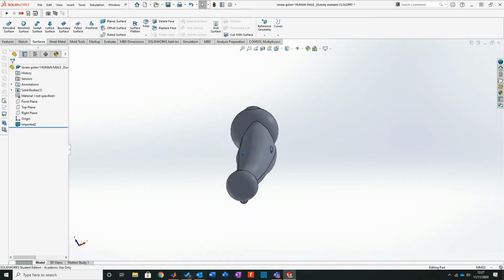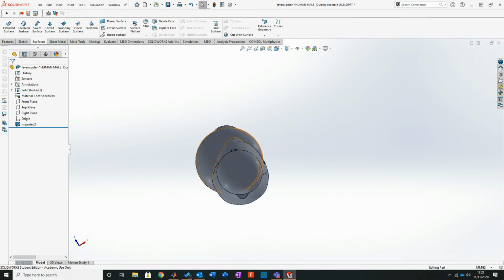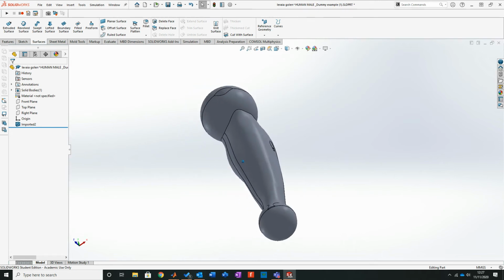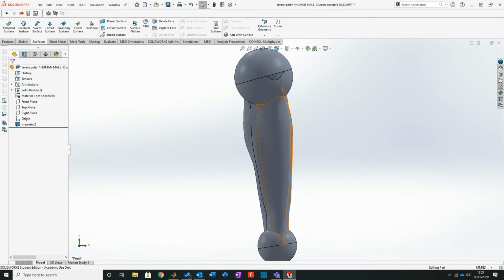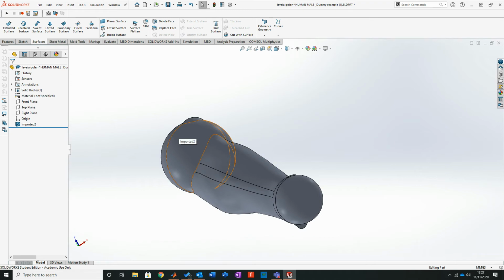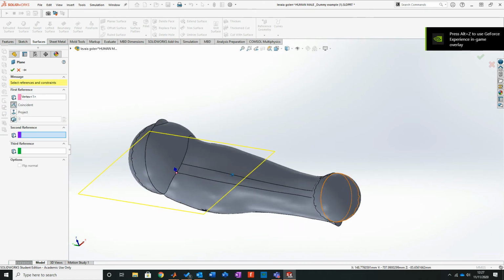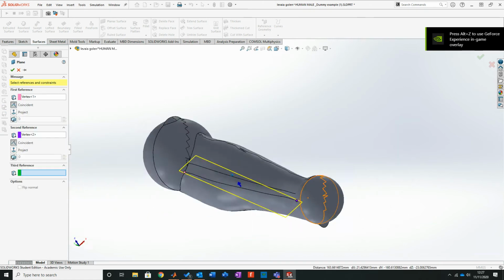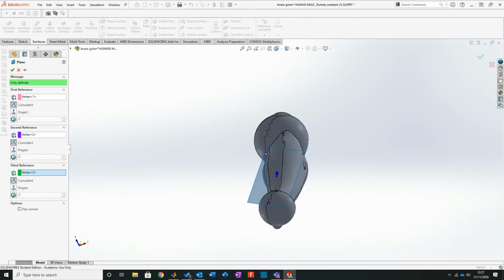if we look at how this has been done, now if you see here, I've got a point I can actually look at. So if we consider this angle to be our point of attack, because you must admit, when something comes in, if you have a target to operate to, if I go like that, you look and go, well, the leg's not straight. You go, brilliant. So what you've got to do is try and build your planes to operate around it. So I'm going to go reference geometry and plane. I'm going to go from that point to that point to that point. And that then gives me what will be the equivalent of your front plane. So click OK.